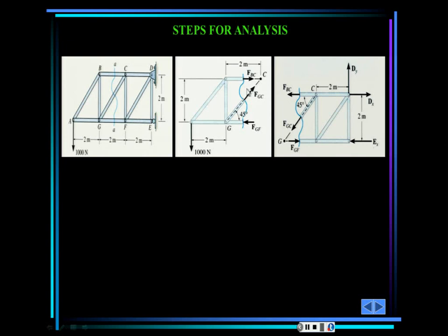Now we have an extra equation, which is summation of moments. That's why we can cut up to 3, we can have up to 3 unknown forces or unknown bars when we apply the method of the section. So we're going to have summation of forces in X and Y, that means 2 equations, and summation of moments is the 3rd equation. And remember, we are only working in 2D for now.